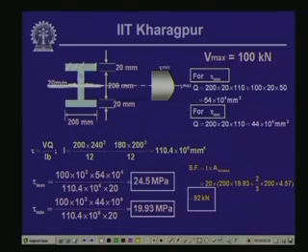Also, we need to compute the shearing stress at another location, the web, as we cannot calculate the shearing stress in the flanges using this shear formula. When computing the shearing stress at that location, the area to be considered is this particular part. That is why the values of Q will be different for evaluating the shearing stress here and the shearing stress here.